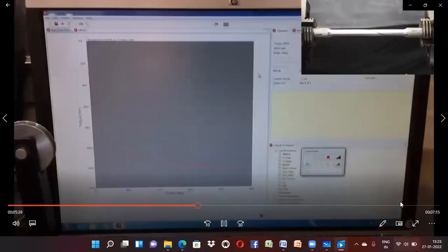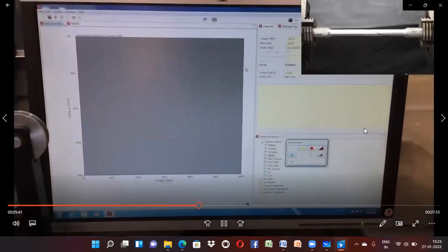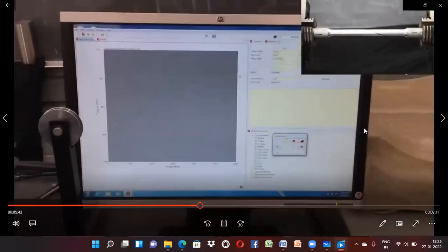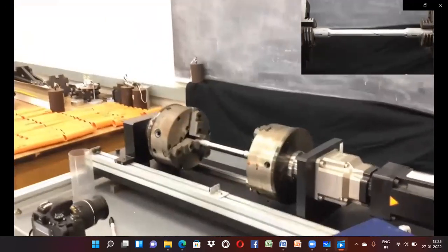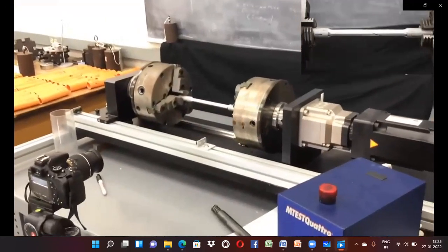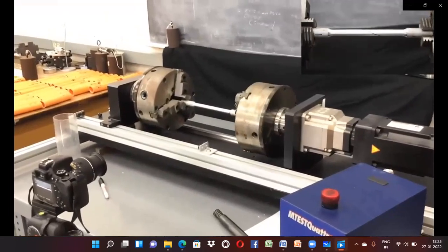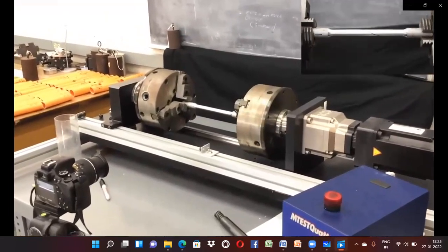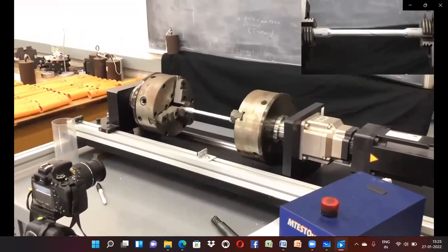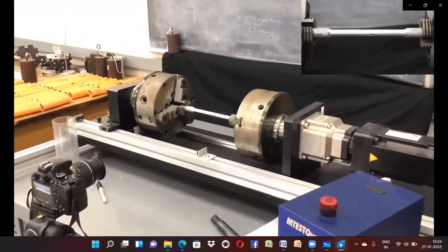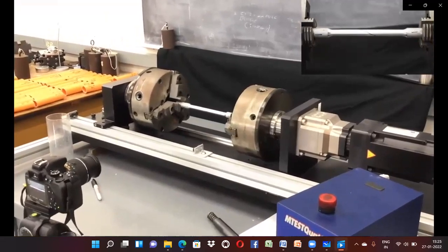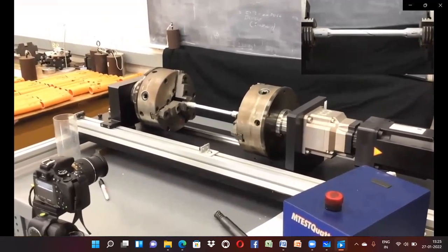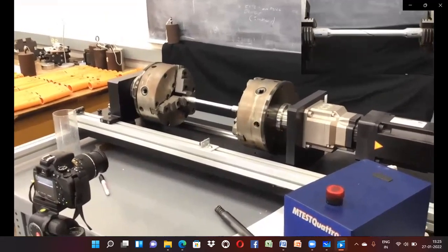So now we're up to, I can't quite read that, 600 degrees, 800 degrees, something like that. So we're almost two revolutions, and we can see that there's almost two instances of the line. We're kind of making a candy cane barber pole out of the specimen, and so we again can see right now the strain, the angle of twist, seems to be pretty evenly distributed as this thing rotates.